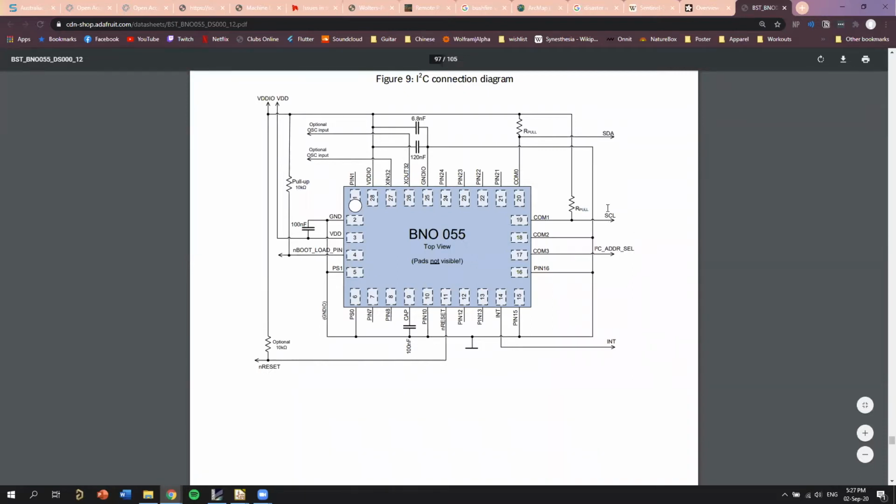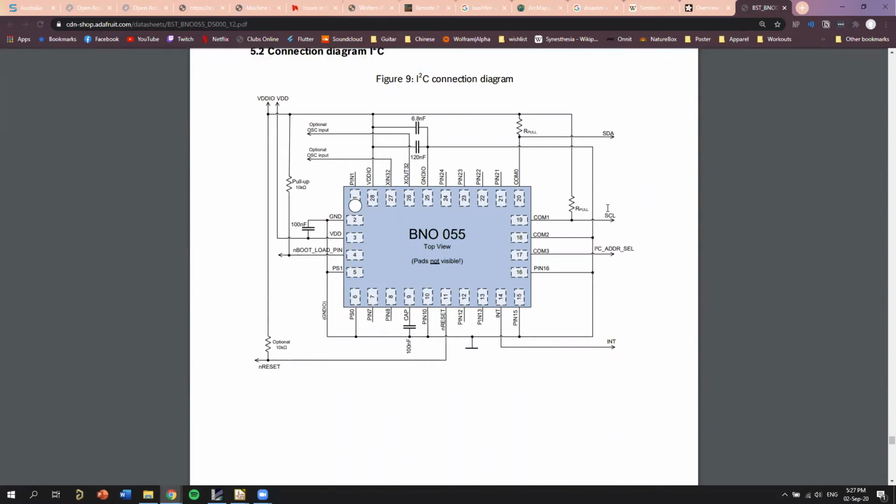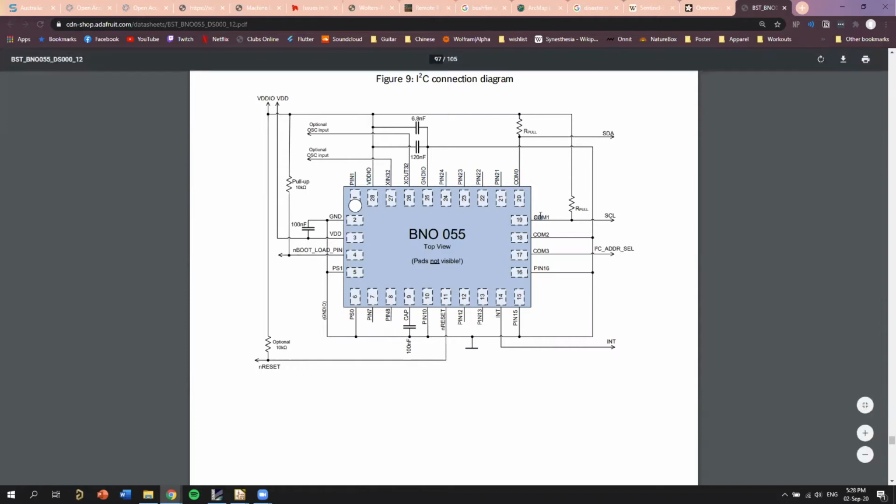I can't explain it the best, but essentially what it does is it ensures that when you output a 0 or output a low from this pin, the signal is actually going to go low. You're not floating, if that makes any sense. So since this resistor is connected to our 3.3 volts, if we put a high here, we're going to get 3.3 volts here and 3.3 volts here, and everything's just going to be high at 3.3 volts.